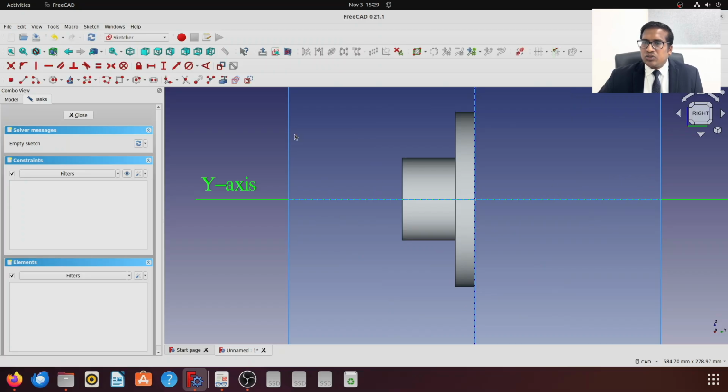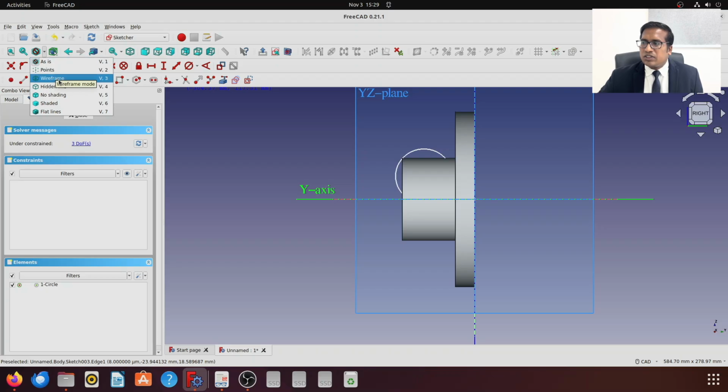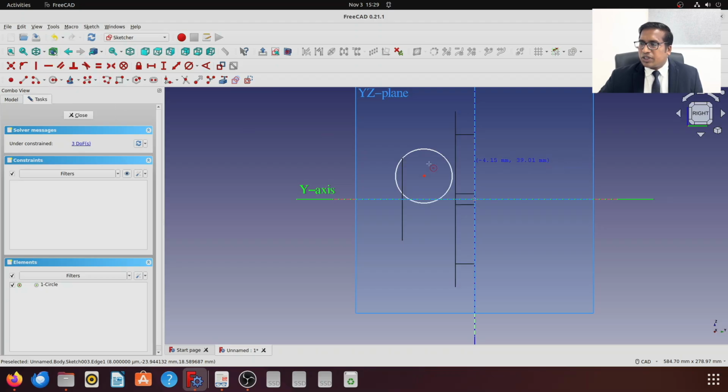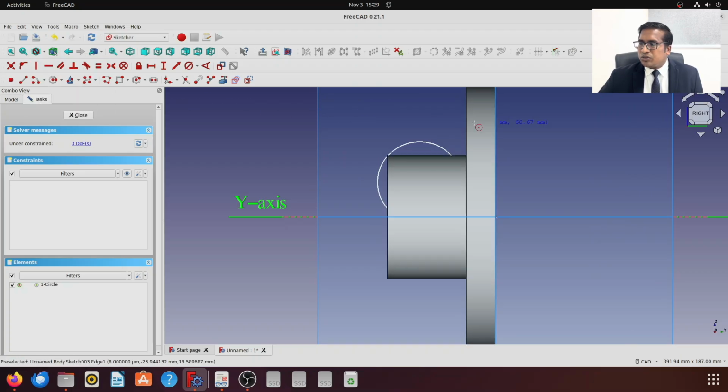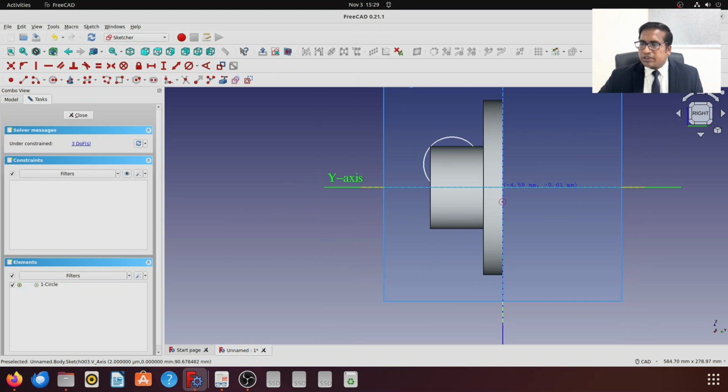While creating a sketch over this plane, I cannot see the figures properly, so I will convert this into wireframe as of now. But before I convert this to wireframe, I need to specify the edges. I will create the left and the right edges.